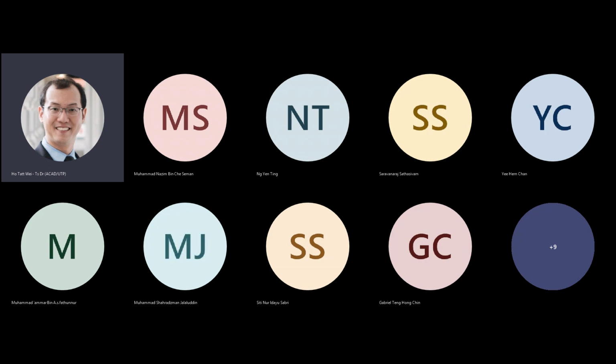So instead of a straight flat channel and a straight flat gate, the gate is this three-dimensional rectangle here. It's got a very high form factor, and the channel is formed across here, from this part all the way going up and coming down like that. And this distance is your 7 nanometer, 14 nanometer, 16 nanometer, and so on.